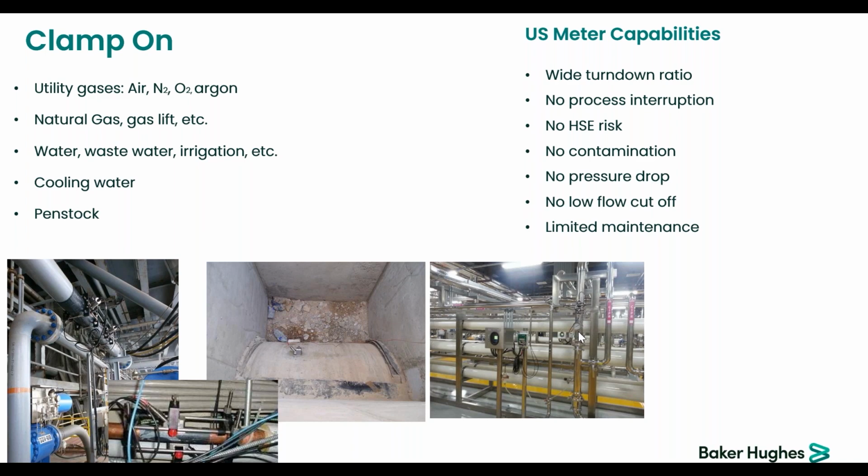If you have SIP, so sterilization in place, and you have steam, while this is water being flown there, which means that when the steam will be used, you will lose the measurement because the transducers are set to work for liquids, not for gas. But the temperature will also be a no-brainer. You can keep the transducers online, although they will not read during the SIP.